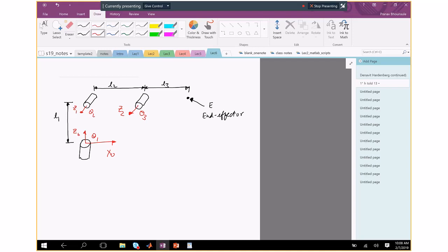What if Z0 is a little bit to the left? Then, yeah, if it is a little bit to the left, then it clearly does not intersect. So how do we know? Well, I showed you L1, and I made sure that everything is in the plane. If Z0 and Z1 were not in the same plane, then I would have a hard time drawing it, but I would draw, instead of a planar figure, a 3-dimensional figure, and show that there's a distance between this plane and this axis. So I'll move it slightly up, and it'll be 3 dimensions. So there'll be an L0, L1. In this case, since I've not shown anything but L1, it means that those 2 are in the same plane.